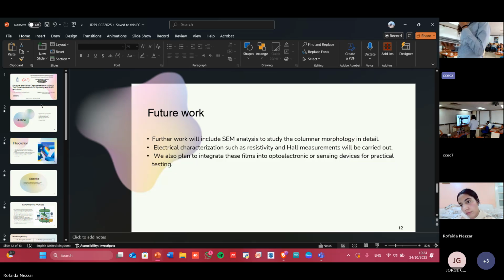What limitations are there in using a combination of two techniques like sputtering and the other technique, in terms of the stability, reproducibility, and uniformity of the deposition of the thin films? I think DC, if we're comparing with radio frequency, is a good method if we want to deposit conductor materials.